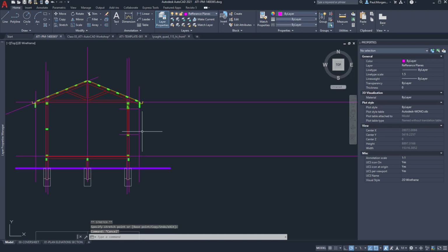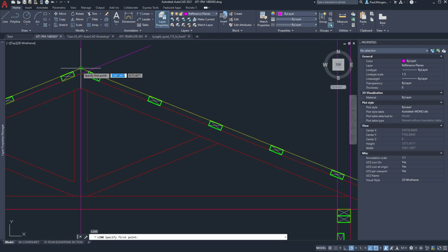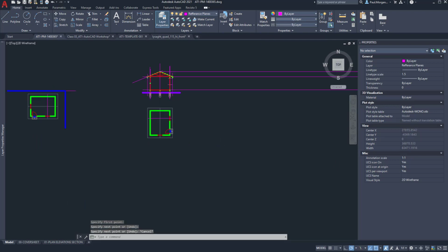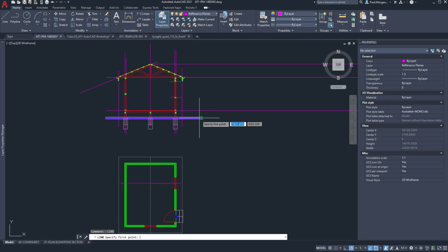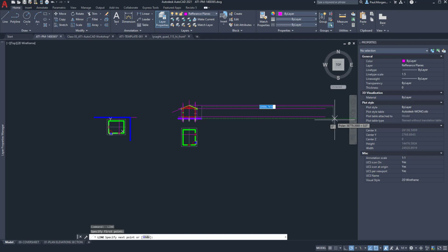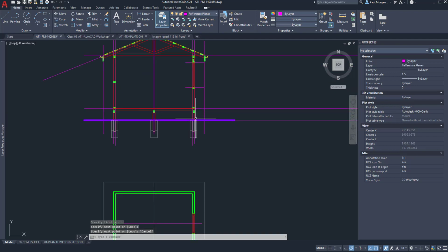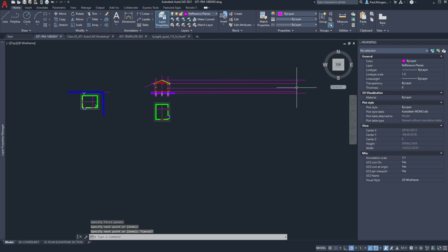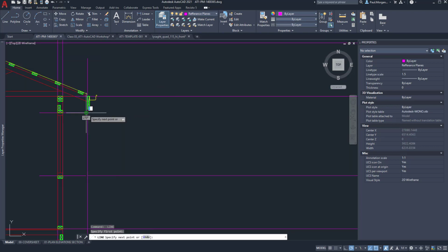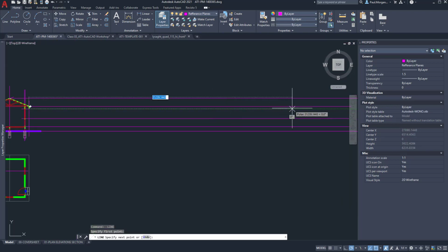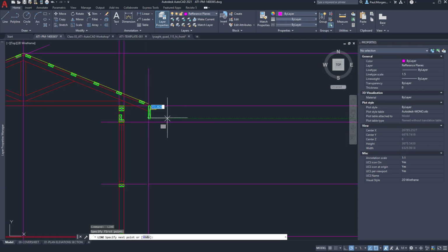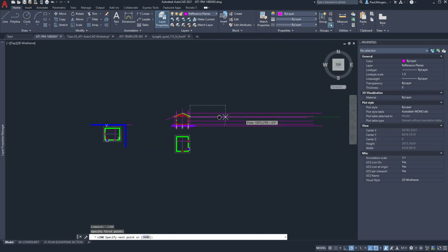And there's a couple of other things that we could be doing here too. So we'll take the peak of our roof, and I'll extrapolate that out. We have our ground, our natural ground level. And then a couple of other things is around window heights. So I'm going to draw this across. And then the top of our window height, draw that across. And the bottom side of our fascia board, draw that across as well.